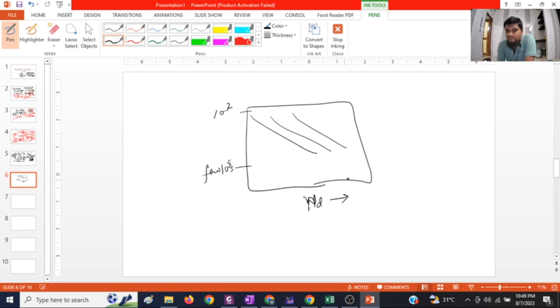So that depends. This side you can have 10 to the power 18, this side you can have 10 to the power 14 or 12. So more intrinsic type of material will have higher breakdown voltage. If it is doped, its breakdown voltage will be low. So let's assume this is for silicon, some for germanium. I don't remember exactly.